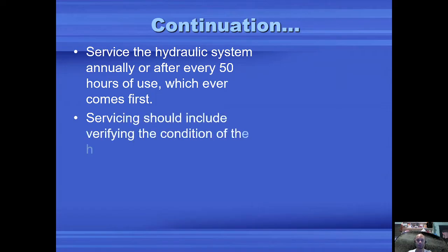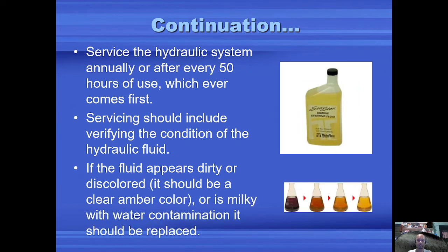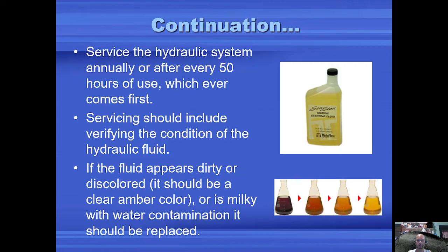Servicing should include verifying the condition of the hydraulic fluid, like checking its color and checking if it's milky. If it's milky, it has water contamination. Then check its viscosity, whether it's still the same as the new one, using the slide viscosity test: sliding the new and the used oil together, and if they move the same, they have the same viscosity.